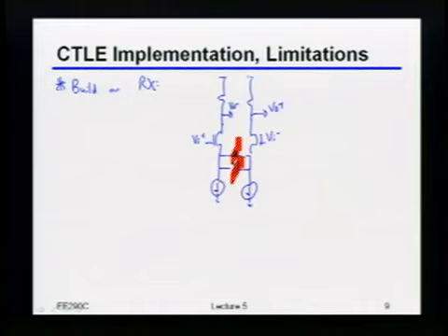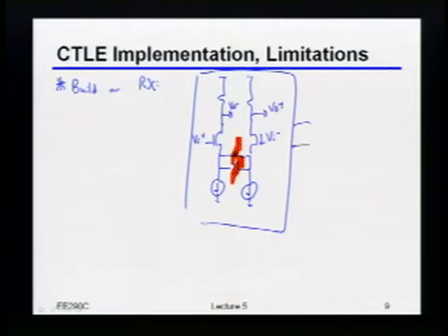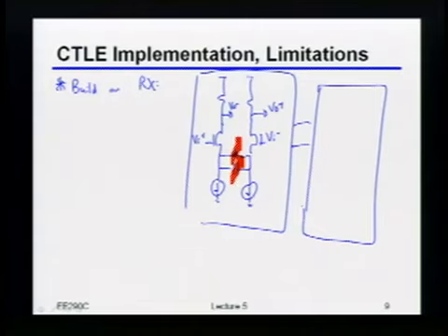How do you get more than 20 dB per decade of slope? Add one more zero. Okay, you said you could add another one, right? Indeed, you could, and just because I'm lazy, I'm not going to redraw the whole thing. I'll put a box around this. Indeed, you could take that and build another one like this. That's certainly true. Is that okay, or can we keep doing this?